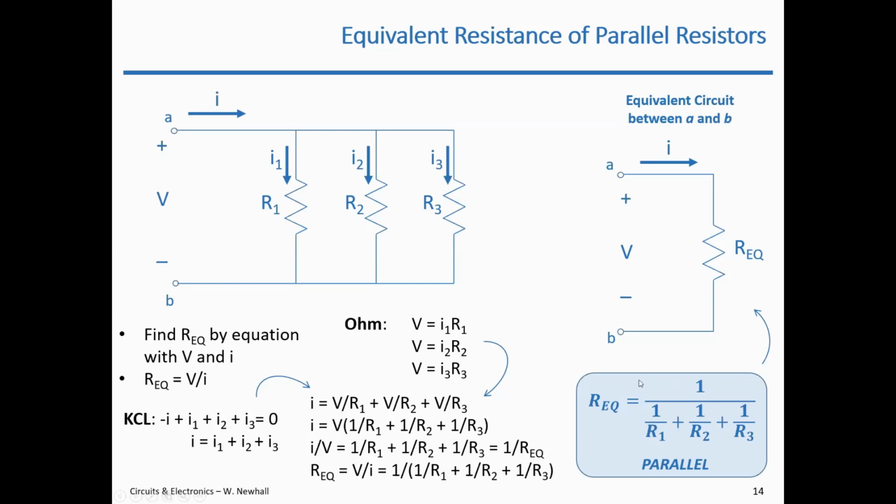I actually recommend not doing that because that only works for 2 resistances. So if you have 3 resistances, you have to do an intermediate calculation and combine resistances one at a time. It's a slower way, and it's also prone to error because I've seen mistakes where folks will try to apply that multiply over add formula.